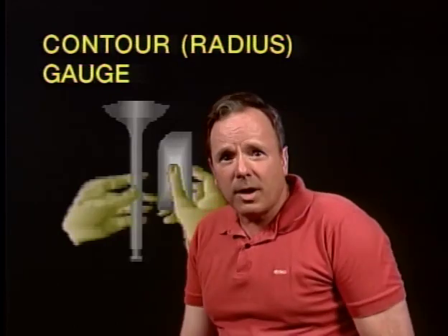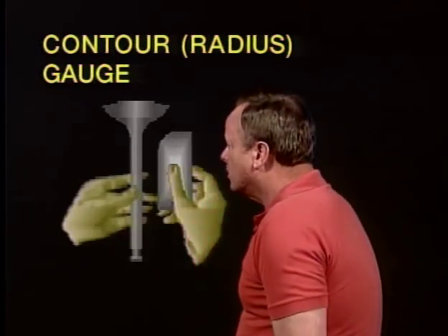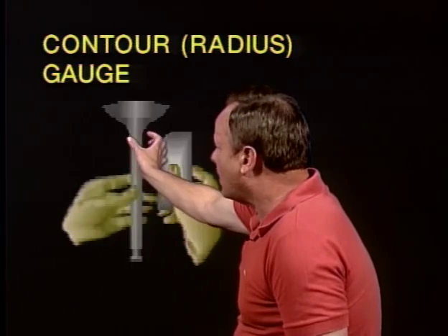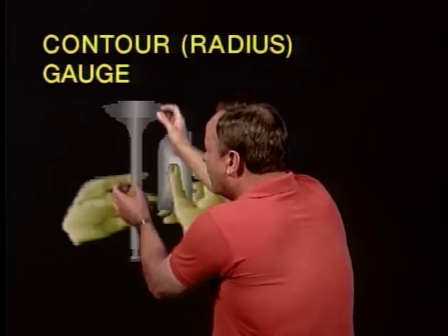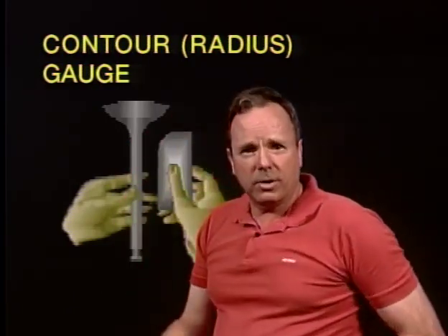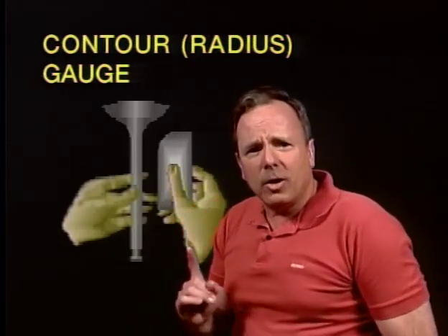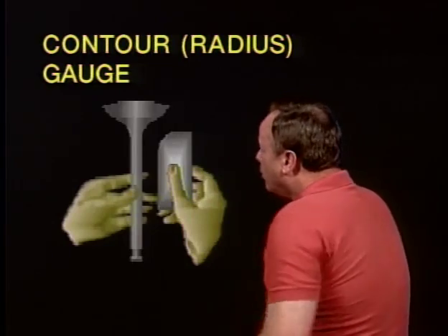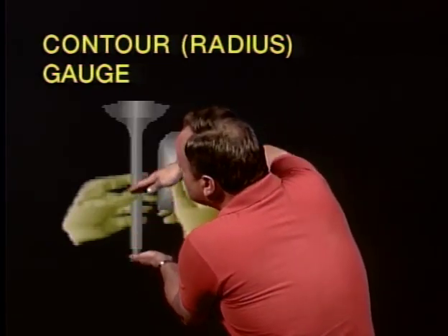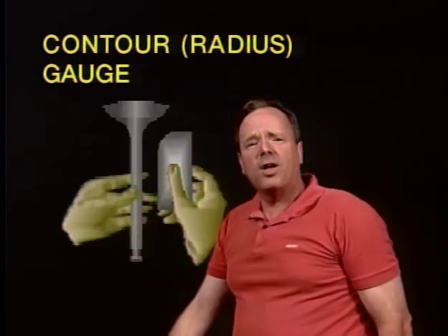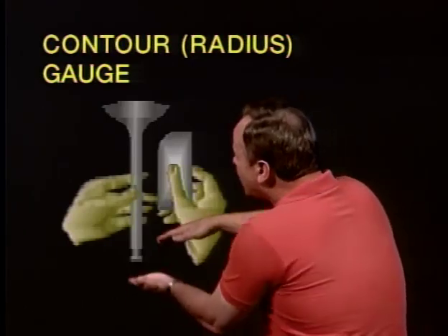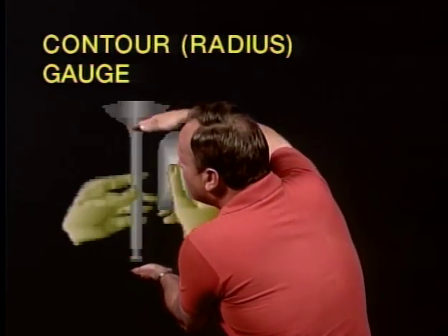Now, another method you could use to check for stretch is you could measure a reduced stem diameter. If it's stretched out, the stem got thinner, and therefore it would tell you that the valve had stretched, and you do that near the neck. Now, here is something that is surprising. Here is a way that is not acceptable to tell if a valve has stretched, and that way that is not acceptable is to measure the length of it.